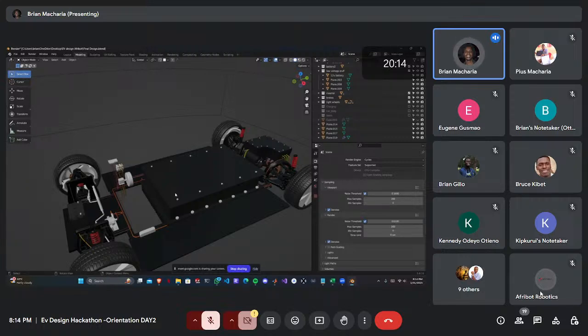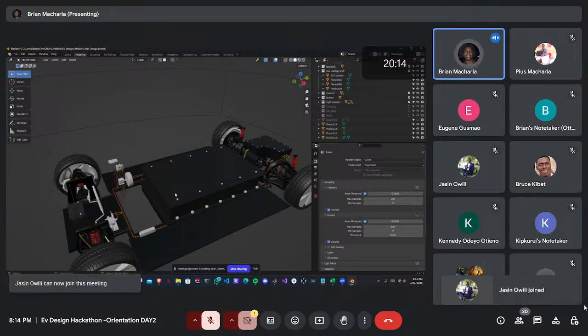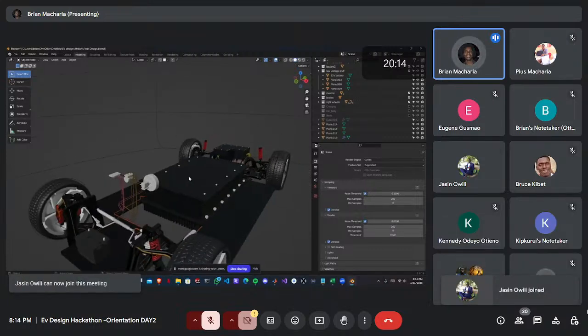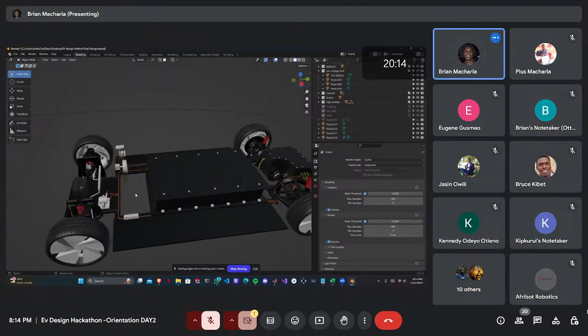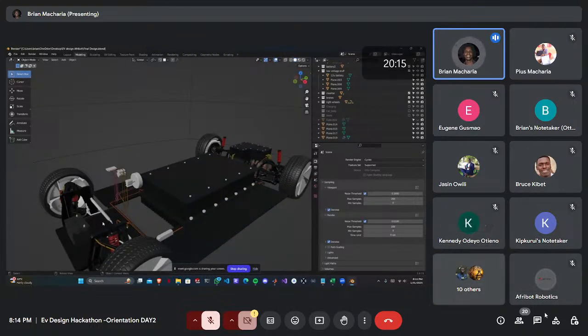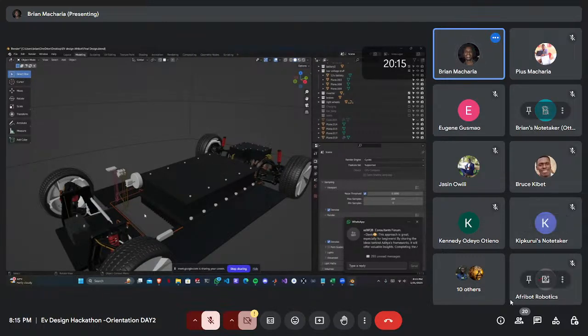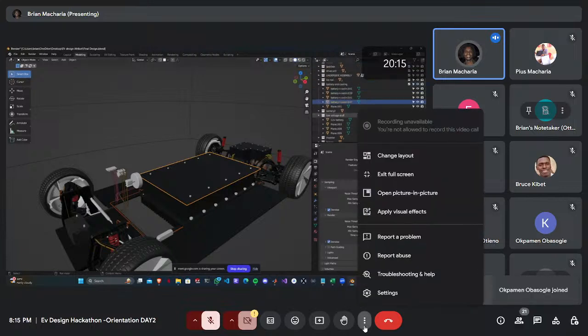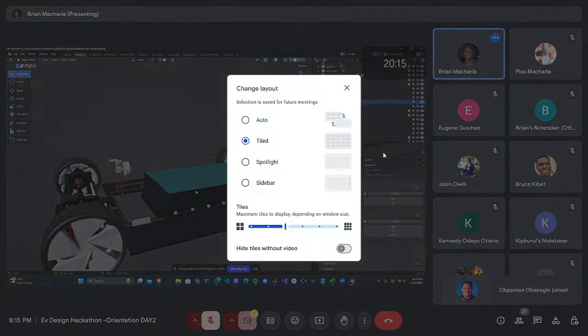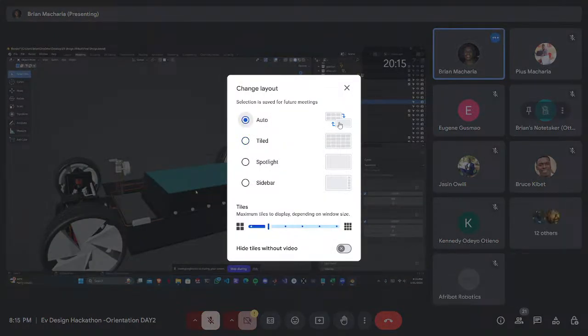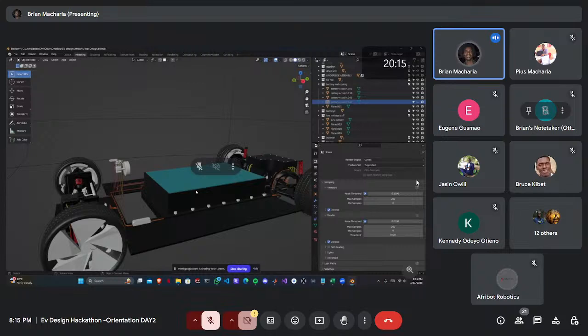So first of all, the casing is designed to ensure that the battery is safe from heat. In this case, the battery holder has a sort of heat sink at the bottom. Air flows from the front and passes through the sinks, providing additional cooling to the batteries. Then if I remove things in the battery, there is a top layer. This is a foam material that dampens vibrations, providing additional protection to the battery.